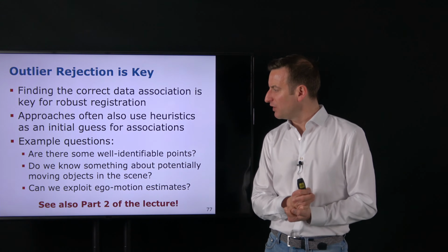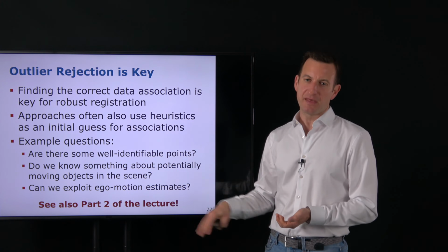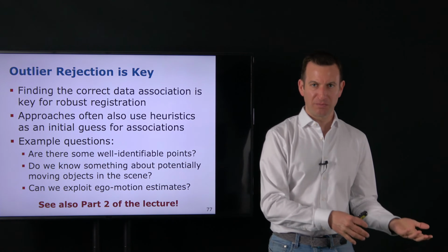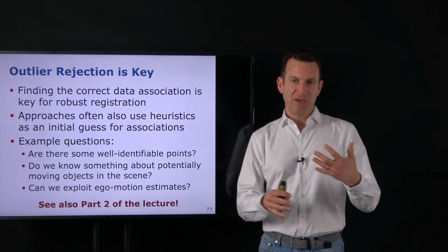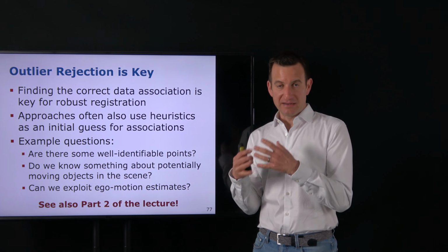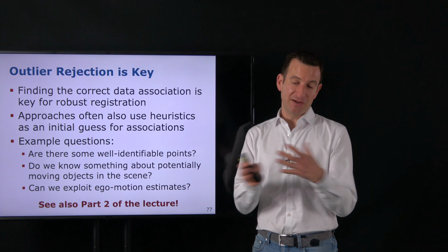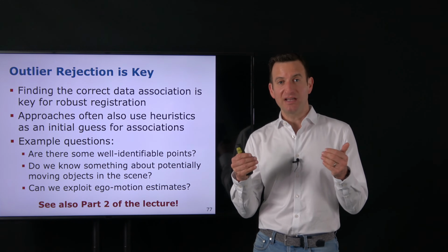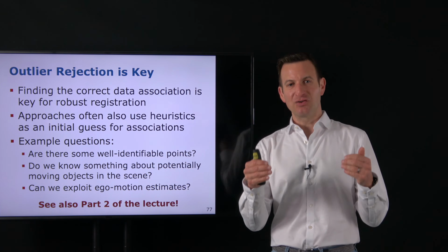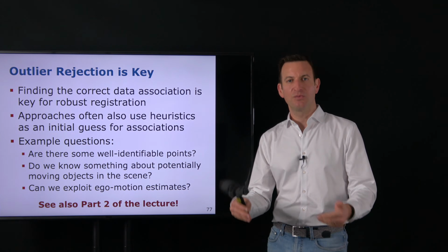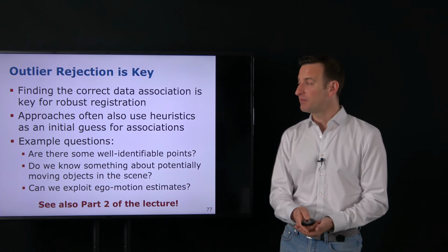What you can also do is, if you build multiple of those techniques, let's say you take the point-to-point algorithm, you take the point-to-plane, you take the symmetric one. Maybe you have a strategy where you say, okay, let's take additional knowledge into account and estimate the pose. But maybe I also want to have a more general approach which also performs well in other situations. So you can actually build multiple registration techniques, or multiple, what we sometimes call sensor odometry estimation techniques, where you use sensor information in order to estimate odometry.